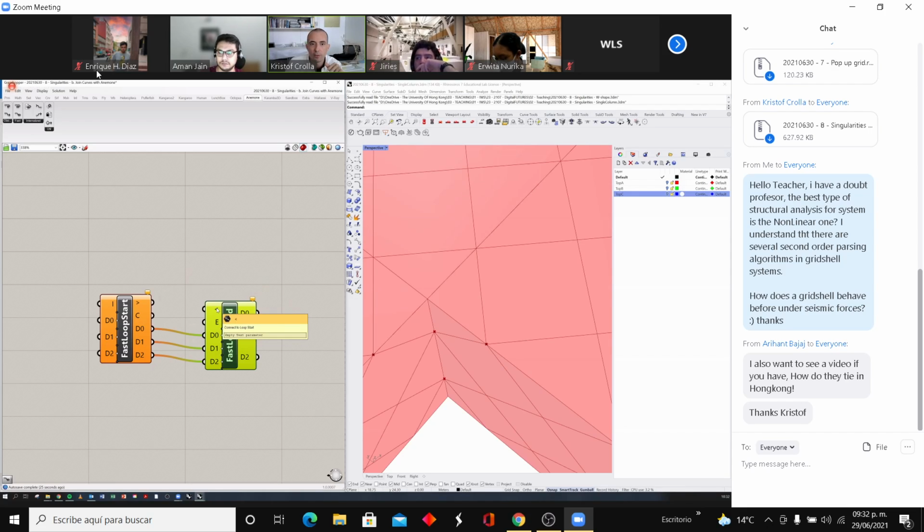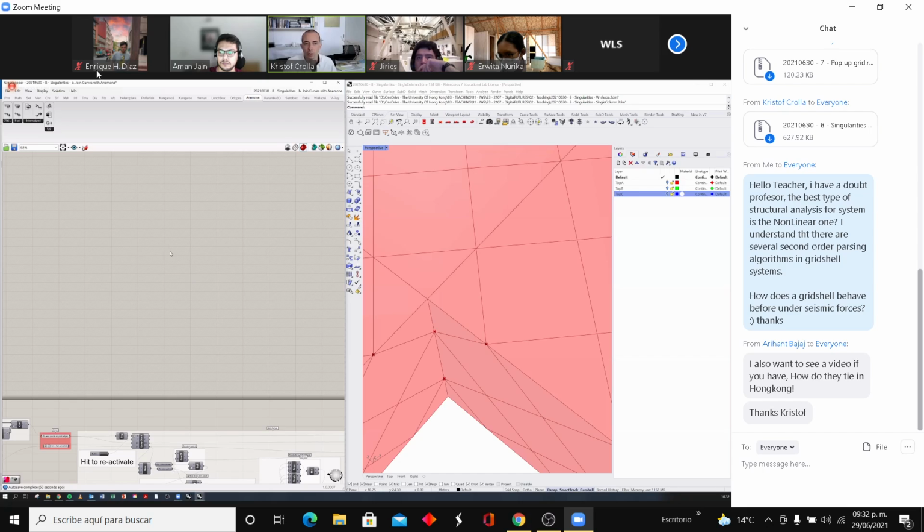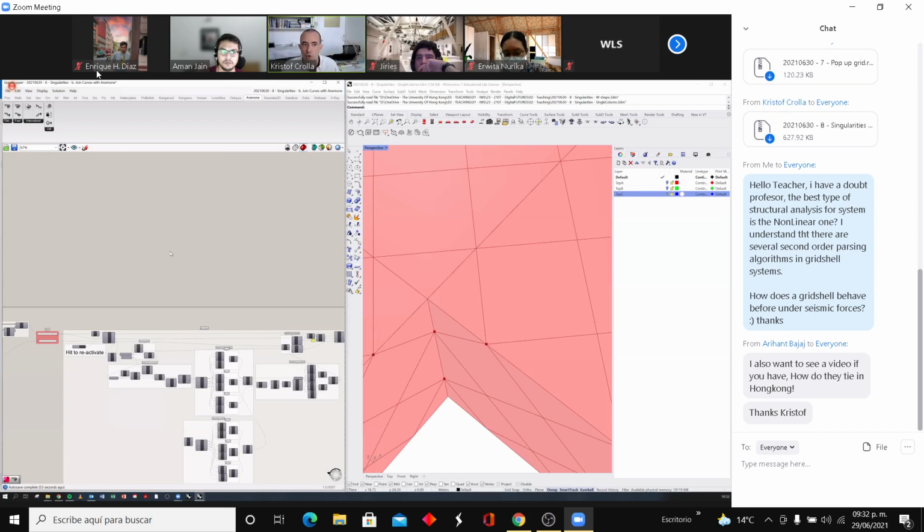Here, you can choose to end your loop at a certain amount of iterations. I mean, there's different ways, but that's the basic concept. Whether you use the classical one or the fast one, they're both similar in the amount of iterations that you're working with. There's other plugins that do this, like Hoopsnake, but Anemone is really nice because it updates automatically. You don't need to have any buttons in there. If you change your input geometry, it will automatically run through the whole script.